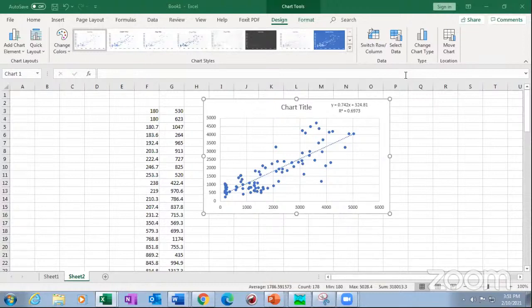So for a catchment like what we are seeing, we have to define a limitation, a maximum value and a minimum value. If you define those, the other calibration parameters will have an impact, and these will adjust according to the discharge value. So this is how you can move on.